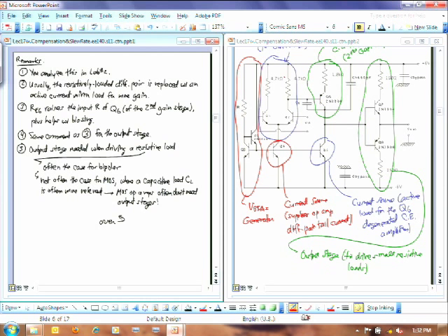If you use an active current mirror here on a breadboard, you would generate such a large impedance right here, such a large resistance, that the breadboard capacitance would be too much for it. And the 3 dB bandwidth of this thing is just going to be too small. So that's why you're not using an active current mirror for this. You're just using these two resistors there. But that is a design all in itself, right? It actually allows you to achieve a reasonable amount of gain in this first stage.